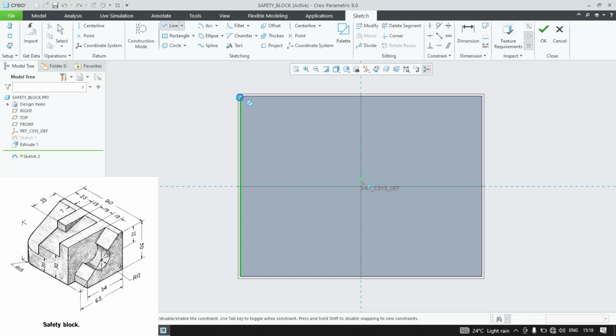The first thing is I'll draw the top portion. So distance is 7 mm. Up to here is the portion which I'm going to remove. The dimension from this point to this edge is 7 mm, right? And he has given the distance from the bottom edge to this point, it is 20. Okay, these two are sufficient for this.